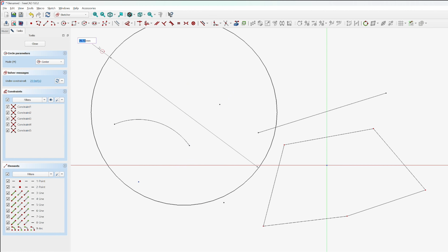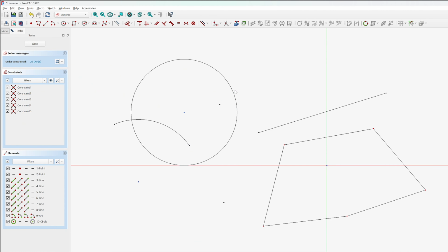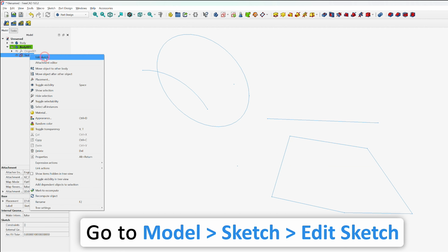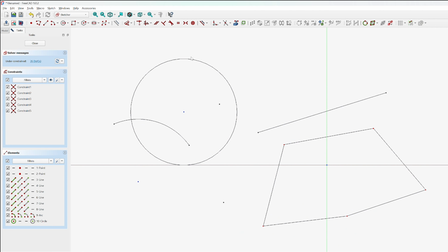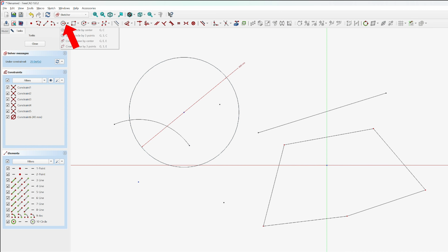Here we have this circle. All you need to do is select the tool and then specify the value of it. In order to define the value, we need to click on this dimension tool. Once we hit dimension, you can see I can specify the diameter value. Now if we go down, just like what we saw in the case of arc, here we also have elliptical circle available.